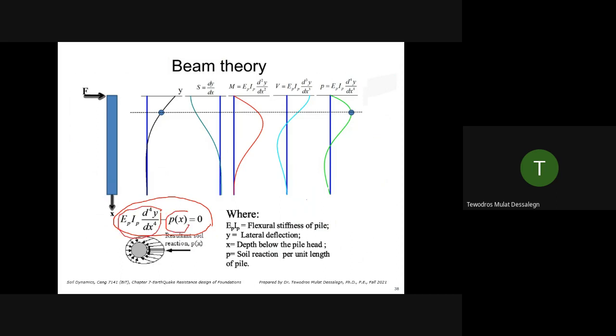So you can have a slope, and for a pile, the moment is given by a second order differential equation, then the shear force, and the pressure finally. This is what's applied in PY analysis of a pile. Basically, we are integrating this equation, finding a solution, and implementing it in software. This is not something easy to do by hand, but there is a numerical solution for it.